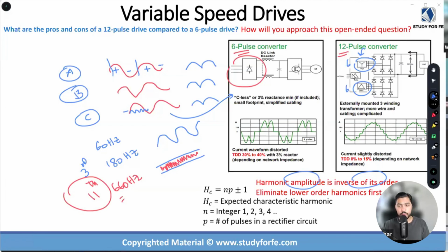Makes a lot of difference because the impact that higher order harmonics make to your fundamental is much less than a lower order harmonic because of the amplitude. Okay. Does it make sense? All right. That's why we don't really worry about high order harmonics. We are more obsessed with lower order harmonics.